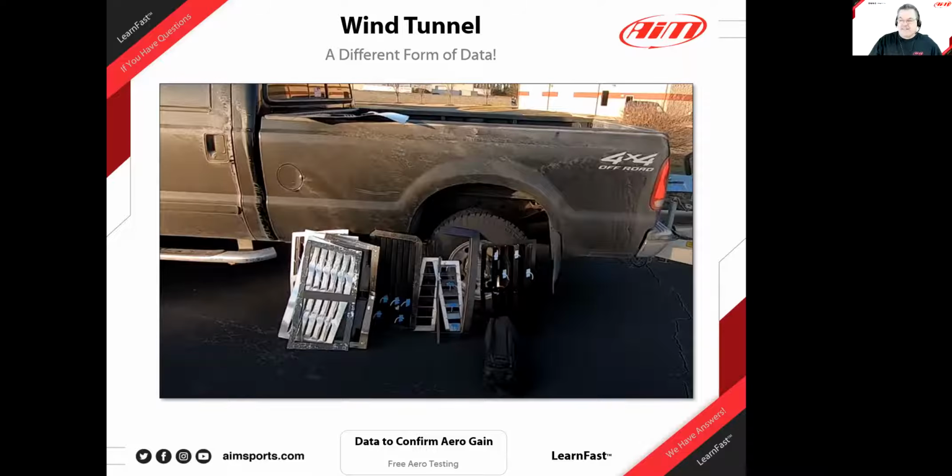Is there a minimum speed below which downforce is not effective, or is that totally independent of the surface and the type? That's kind of a loaded question, I suppose, right? Yeah, a little bit of a loaded question, just because speed is a factor in downforce no matter what. Effectively, at a few miles an hour, it's doing something. But in terms of actual grip to the car, 60, 70 miles an hour is where it should do enough. You should probably feel something, but it's exponential. So the faster you go, the more downforce you start making as well.